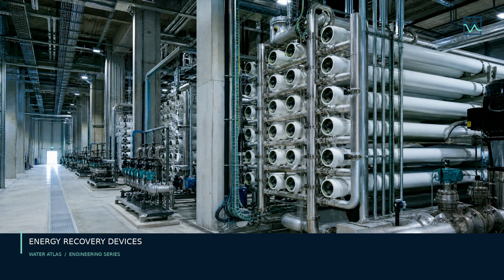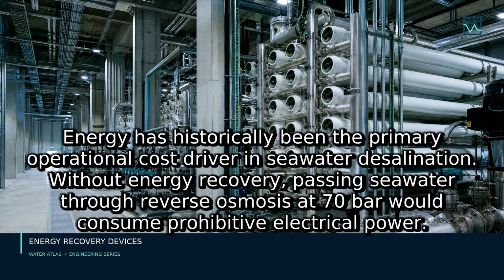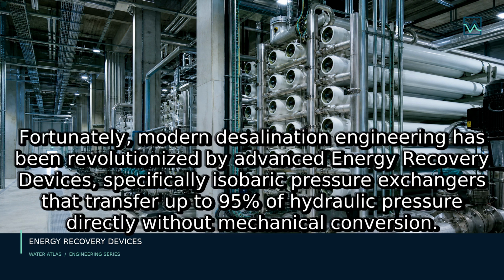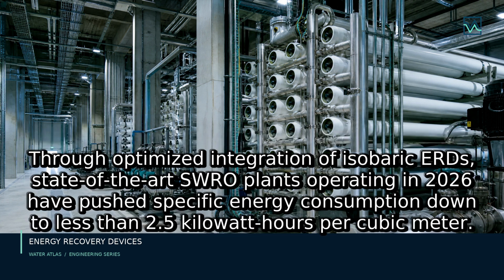To maximize freshwater output and reduce intake and pretreatment sizing, modern design increasingly turns toward high-recovery seawater reverse osmosis, or HRSWRO. Traditional single-stage SWRO plants typically operate at recovery rates between 40 and 45%, meaning more than half of the intake seawater is returned to the sea as concentrated brine. Pushing recovery to 60, 70, or higher requires sophisticated multi-stage configurations.